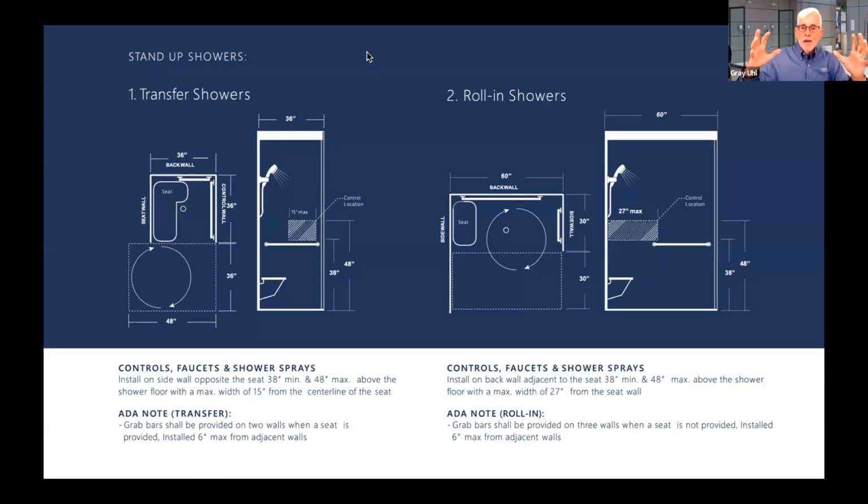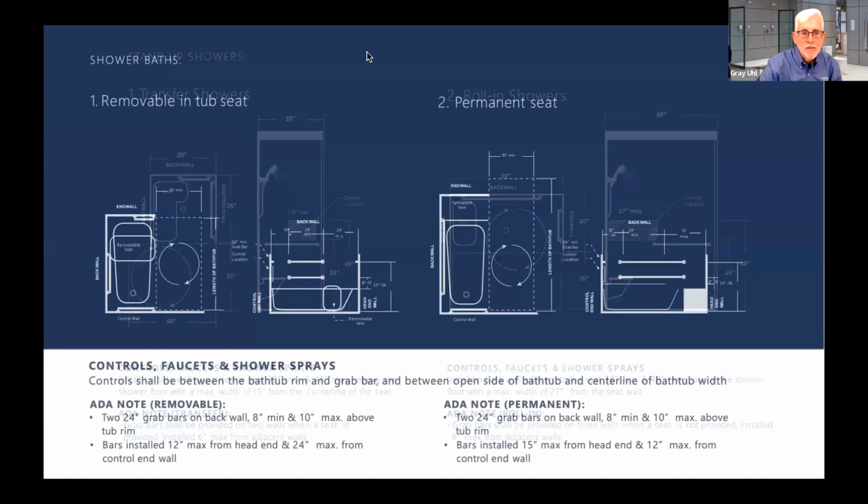Typically in an ADA shower, you need to go oversize on the dimensions of the base to achieve the minimum interior dimension that you're looking for. So just another thing to look for. I know here at Lixil, when we make ADA shower bases, they're these goofy dimensions. It's because they're oversized to deal with the finished product.